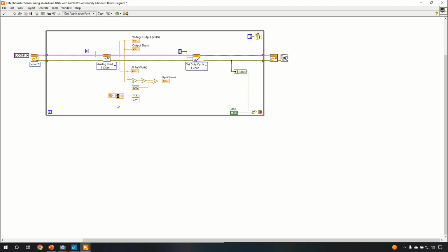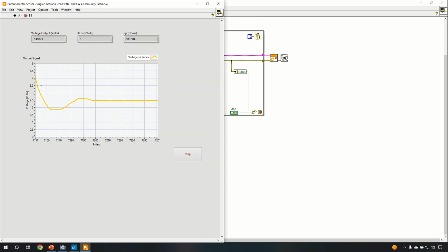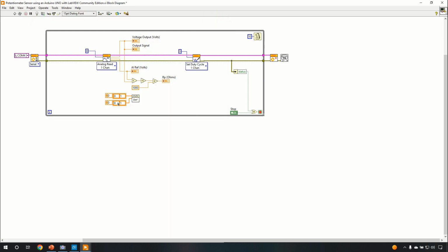We'll have two values which are 0 and 1. We'll just make it a little bit larger. Perfect. We'll copy this one and we'll say for these we'll have the lower bounds of voltage and upper bounds. So let us run our code again. If I rotate counterclockwise, my lower bound is roughly 0.463. So let's say 0.47. And my upper bound is 4.99. So let us put here 0.47 and here 4.99.